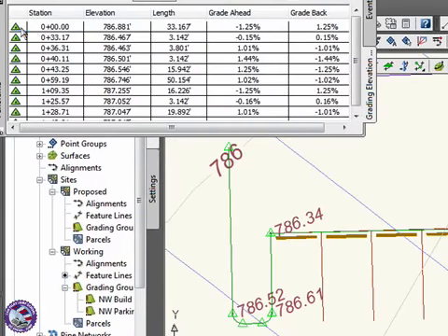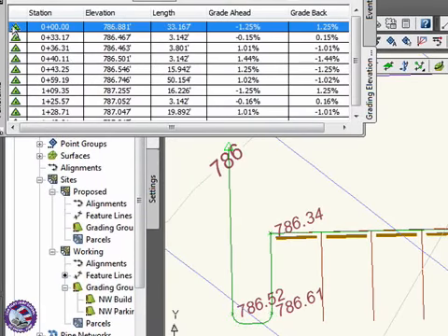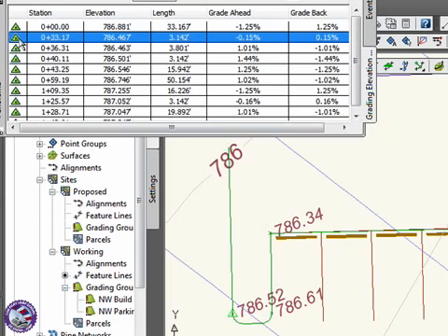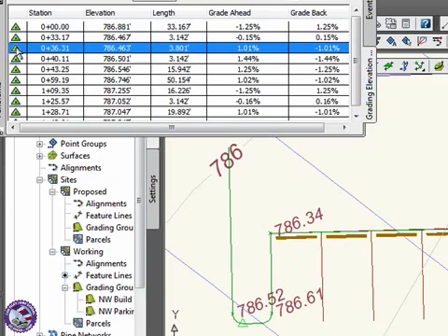you can see as I pick my first station, my little triangle shows up right there. And so I could work my way down here, and what I like to do is I'm going down about 1.5%. That's great. Coming around this corner here, right? It's nearly flat as I make the corner, and I'd like that to be a 1% grade going up that way.